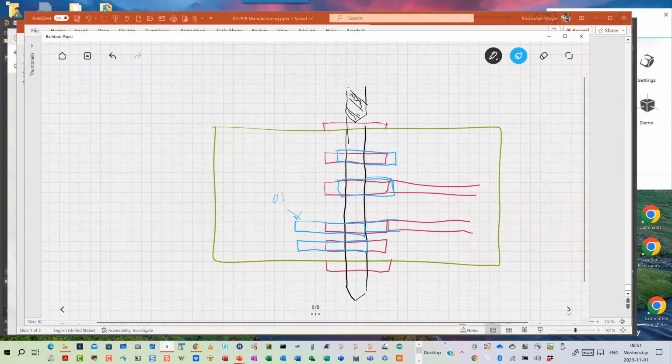But over here, when I get to this one, as that drill bit's coming through and hitting the edge, that drill bit might actually try to wander a little bit. It's going to kick off sideways rather than trying to continue down. So basically, the fabricators like to remove all of these non-connected, non-functional lands like you've got here and here, for example.